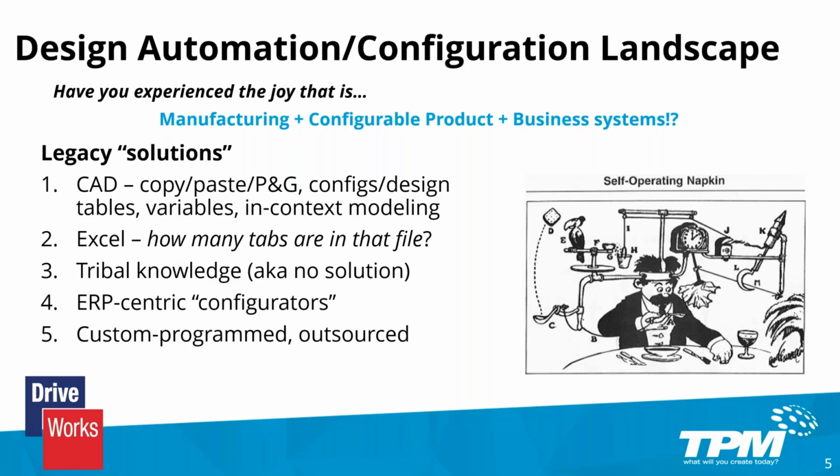Folks who are from the engineering realm know that there are some options within CAD and specifically within SOLIDWORKS. If you have one job one day and then the next day you have another job that's similar but different, you might do something like copy and paste or Pack and Go of a file set, and then tune up the pasted file set, or you might have heavy use of configurations and design tables or variables or even in-context modeling.